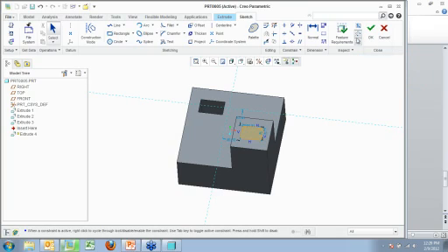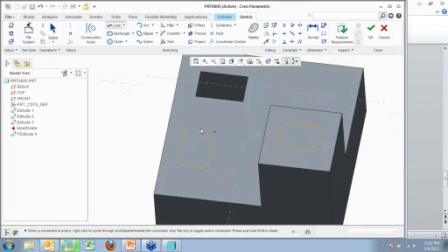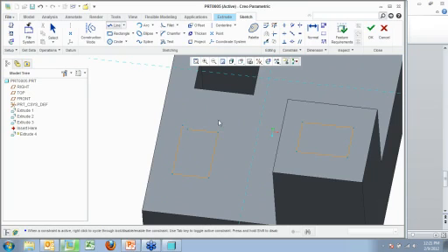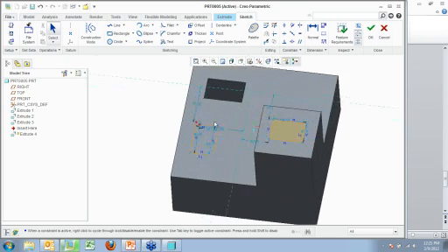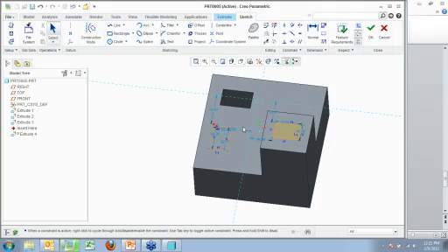So when you're editing a sketch and you change something so that it's no longer closed, let's say I'm sketching a square over here and my ends don't quite mesh up the way I want them to, now you can see it's not shaded because it's not closed, and also it's highlighting the two open ends. And that's really useful when you're editing a lot of geometry, when you're going in and deleting part of a sketch, because you want to change the shape of an extrusion or a revolve or what have you.